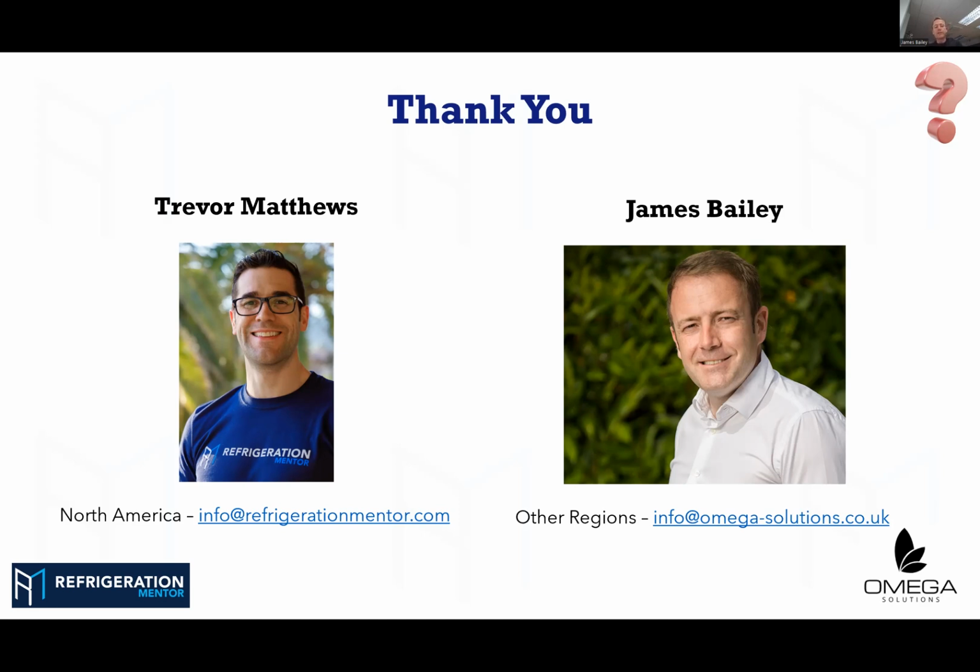But when we're talking about the pressure we've got to overcome, it is daunting, and you do have to apply extra layers of caution. But from a design perspective, in all the CO2 systems I've designed, I've never had to use a double riser, no matter how much duty, because it's always going to return oil. Even if it's just a couple of fixtures on a big island run in a supermarket, even with a really poor defrost schedule, it's still going to get it up, because as you say, we're looking at 20, 30, 40 bar in the suction line. So you're always going to get the oil coming back up on the inside of the pipes. Plus the pipes are smaller.